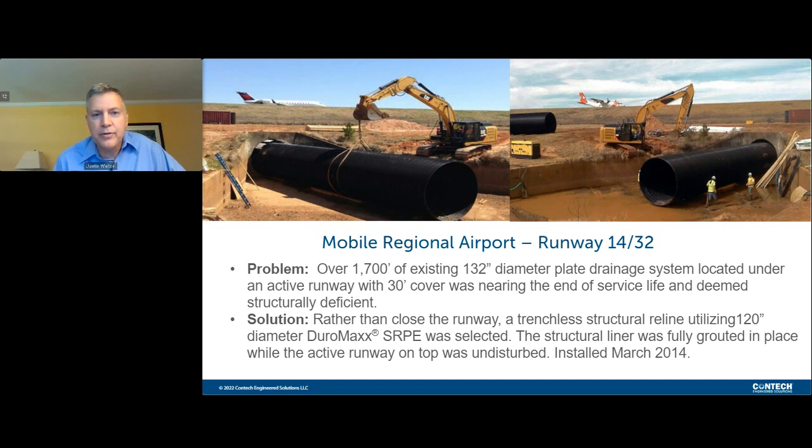And because the Duramax liner pipe is also a direct bury pipe, that means that all of the loads applied to it, the dead, live, and hydrostatic loads, could be handled by the liner on its own. The host pipe may have some structural integrity left. Maybe there has been soil consolidation above the structure over the years, forming a soil arch to help reduce some of the loads on it. And if so, that's great, but we want that just to be insurance. And we use the full gamma H from the crown of the liner pipe to the surface.